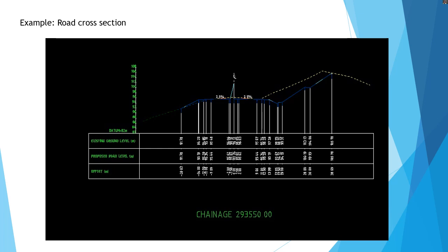And if you build this road lower than the existing over here, you have some cuts over here. If your road is higher than the natural ground, you need to fill it up over here to get to the required elevation. So we are going to know the elevation of the existing ground by doing the cross-section survey.